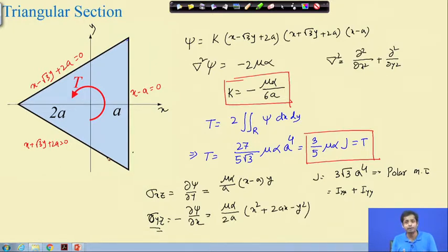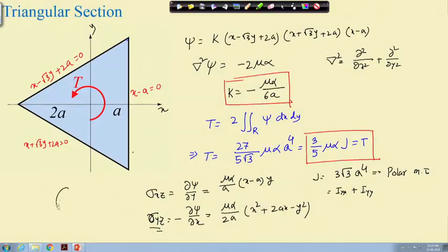By intuition also we can say, based on strength of materials, in the circular shape solution the stress was maximum at the periphery, at the outermost circle, on the surface. So, here also it will be the same, on this plane the stress will be maximum.